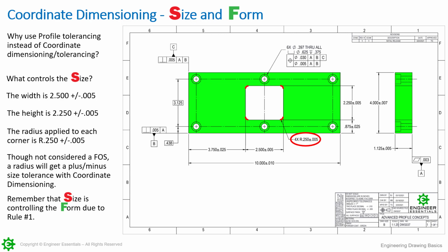Now, they do state rule number 1 does not control the orientation, but we do have envelope requirements for these, both the 2.5 and the 2.25. So we have envelope requirements, and even though there's no rule for the 2.25 and 2.5 to be oriented to each other, the two surfaces do have to lie within the MMC and LMC limits and ultimately that envelope.